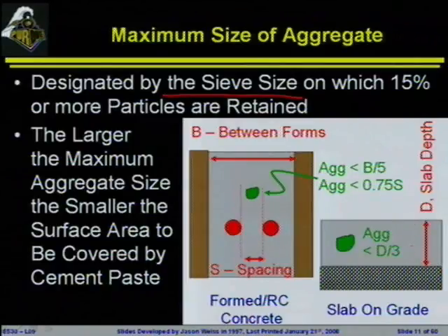Now, this will tend to be a little larger than we use in most other structures. In most other structures, what we will find out is that the aggregate has to be less than 1/5 of the dimension. And the big reason here is if a slab on grade fails, it is simply going to be supported under the entire slab on grade. All right, a sidewalk fails, and you have two sidewalks resting on dirt. If a beam fails or a wall fails, then it doesn't have the same type of uniform support, and this is one of the reasons that there's a difference in the numbers here.